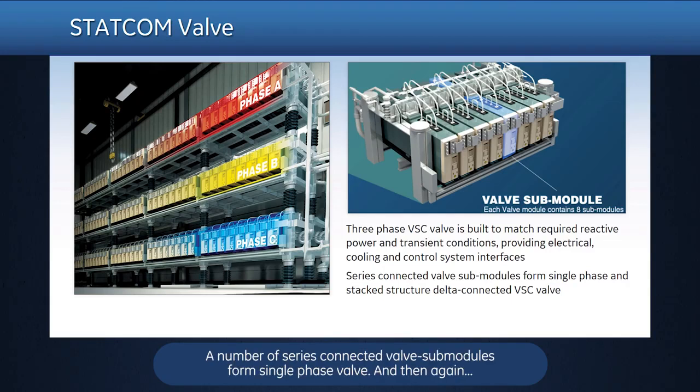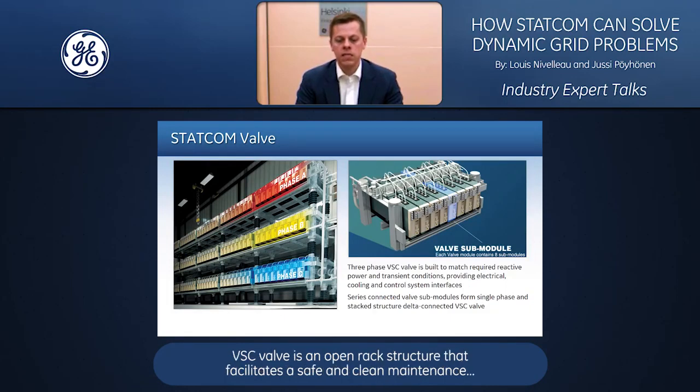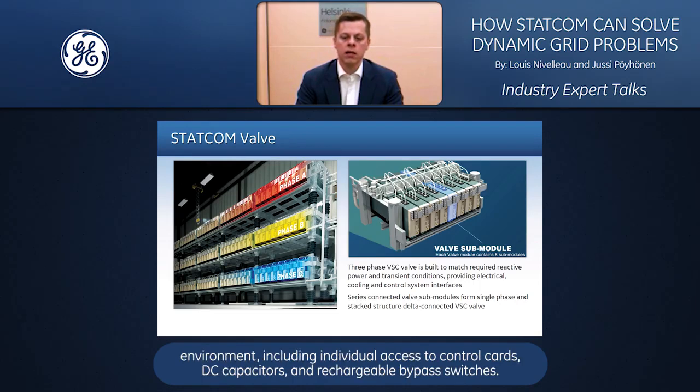A number of series-connected valve submodules form a single-phase valve, and then three-phase valve construction combines single-phase valves in separate tiers to match desired performance. VSC valve is an open rack structure that facilitates a safe and clean maintenance environment, including individual access to control cards, DC capacitors, and rechargeable bypass switches.